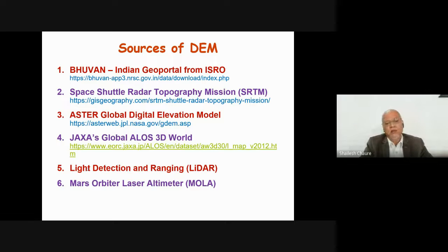So suppose you have a case of road widening, you can just mount a LiDAR on one vehicle and move on the road and collect the data from the sites. So whatever is the topography there, the depressions, elevations, whatever is there, it is very well picked up, and then you can prepare the cross sections and everything from there. The way you do it with your original survey data, you can extract the points from there and have your cut fill calculation design. So this is another positive thing.